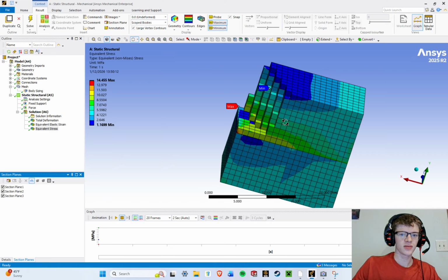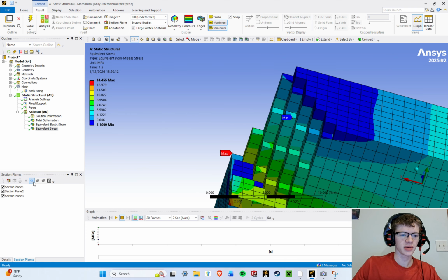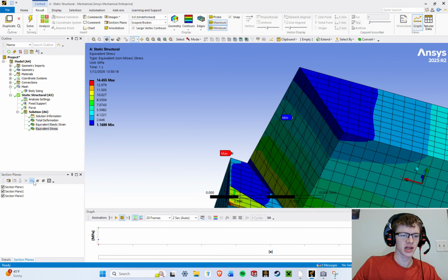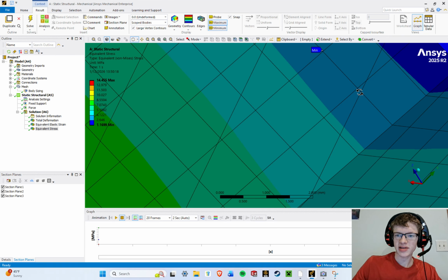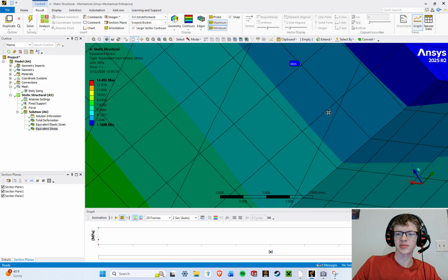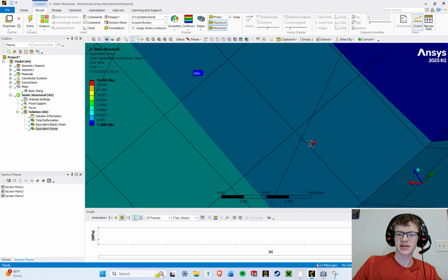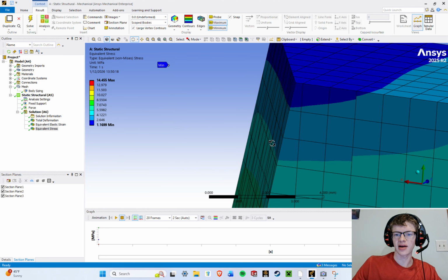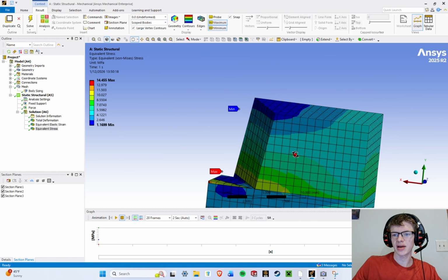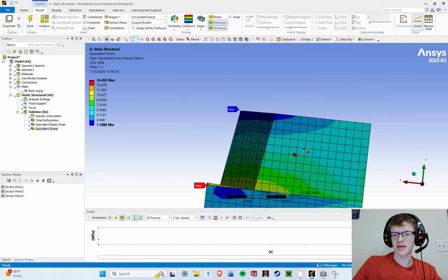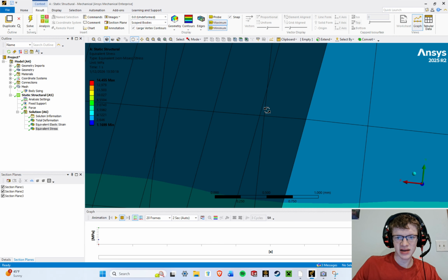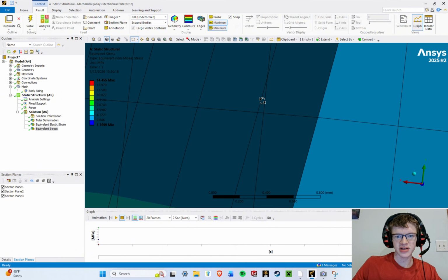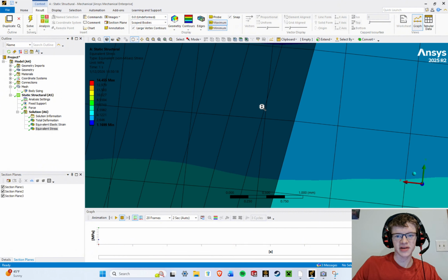This button will show whole elements. That's what it says, show whole elements. So basically, if there is an element and you can see just a part, even the smallest part of it, Ansys is going to show you that entire element. So if we align this like this and zoom in, you can see right here, there's just the slightest corner of this element.